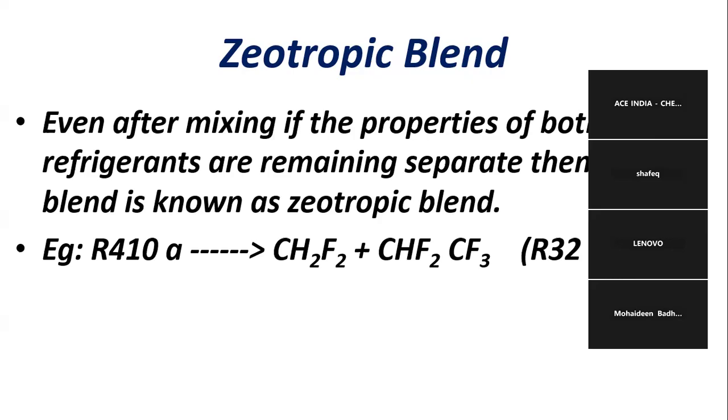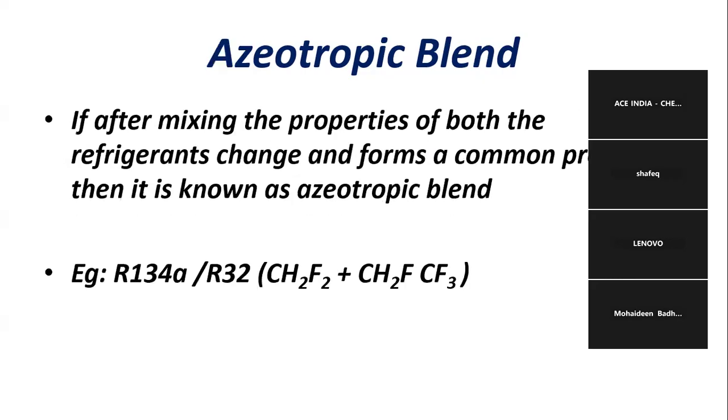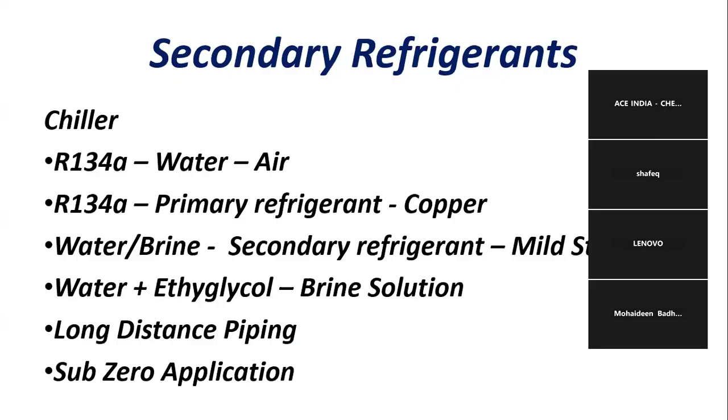So typically, we studied about natural refrigerants, synthetic refrigerants, and blends. And these three are the subclassification of primary refrigerants. Next, we are going to study about secondary refrigerants. As I mentioned before, secondary refrigerants are implemented right inside a chiller system. Generally, the secondary refrigerants that we are using are water, air, and brines. Technically, water can be used as a secondary refrigerant, and it is more cost efficient and abundantly available on the earth itself.